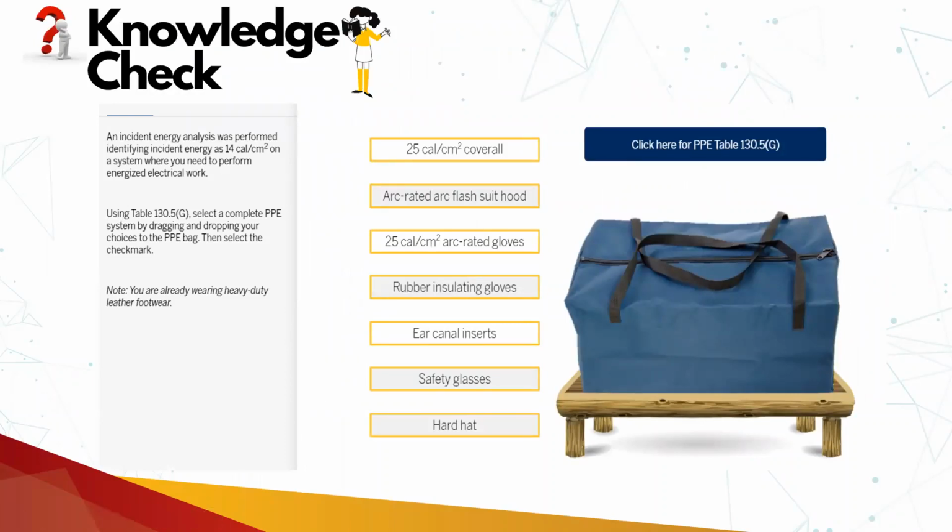This type of question you will also be finding in the exam. For example, they have mentioned here an incident energy analysis was performed and the incident energy was around 14 cal per centimeter squared. Use Table 130.5(G). They have mentioned the table, but normally this is not the case. But let's suppose they are directing you to select the PPE based on this table. So select a PPE system by dragging and dropping the choices of the PPE in the PPE bag. So you are going to refer to 130.5(G).